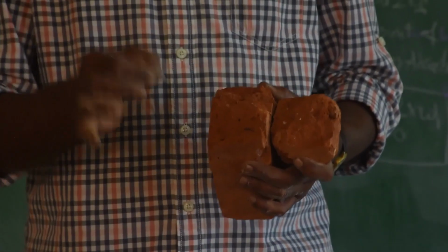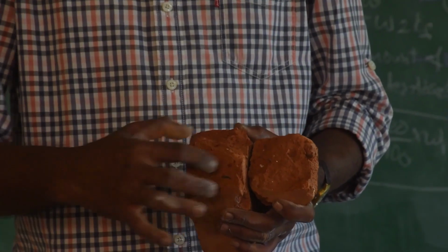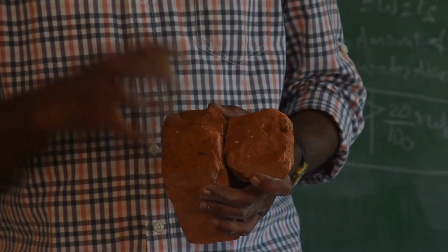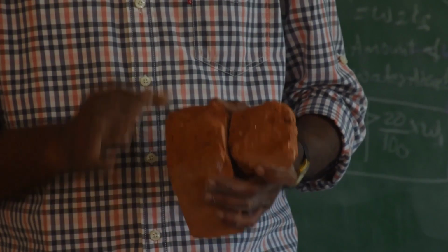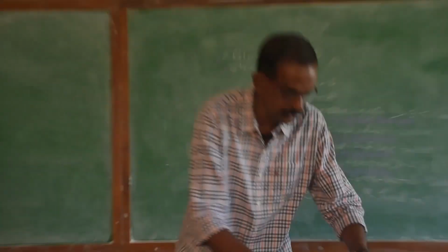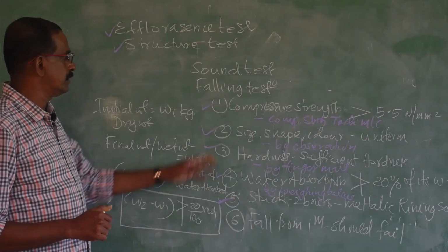So, take the brick and break the brick and study the inside details. It should be free from all the cavities, impurities, organic matters, pebbles, etc. So, these are the tests for brick.